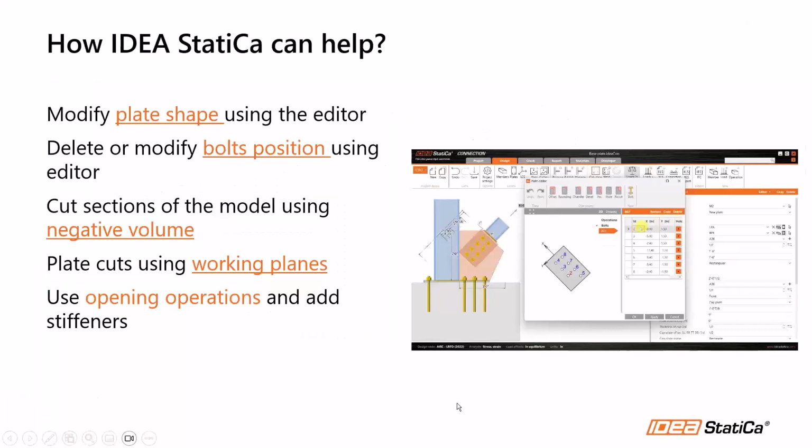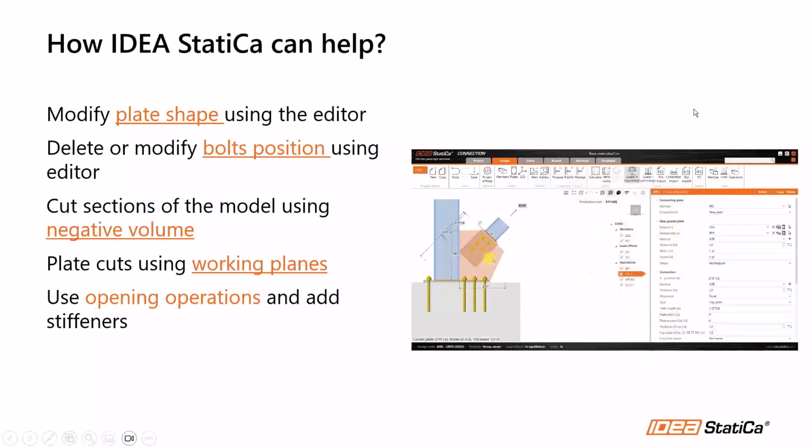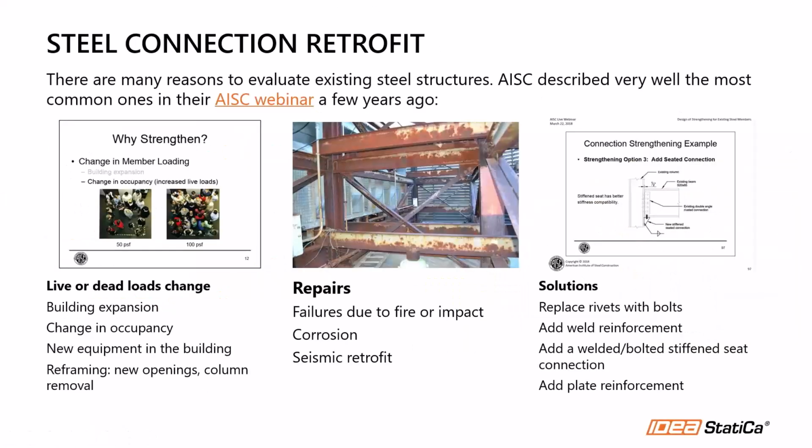All right, let me go back here to this presentation. I showed you how to modify plates or bolts position using the editor, how to cut out sections using negative volume, and how to use opening operations. Okay, now let's continue to the last topic that we have today.